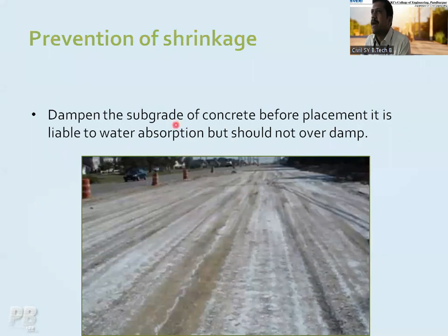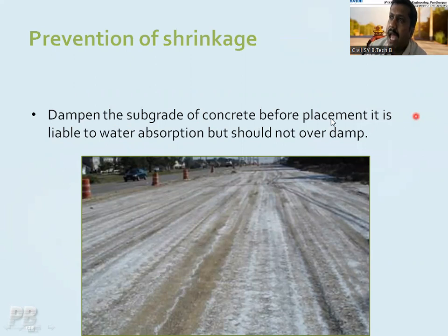You can see the preventions of this shrinkage. How are we going to prevent the shrinkage? Dampen the subgrade of the concrete before its placement, as it is liable to water absorption, but it should not be over damp. Like the DPC course basically.